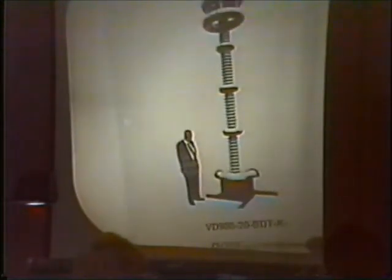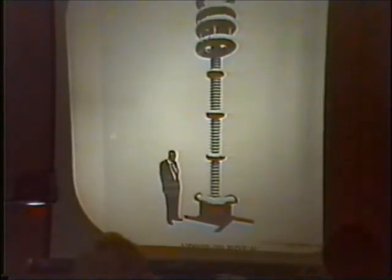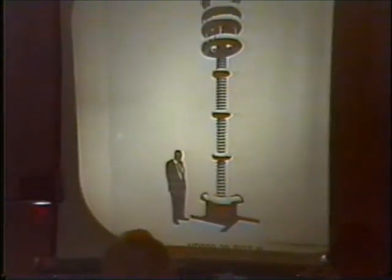Okay, well, here comes the 900,000 volt one. You see that it gets out of control real fast, as to the voltage dividers and the instruments that you have to use and that sort of thing. There's actually a much easier way to do this, and since magnetic flux and electrical flux are part of the same coin, it's real easy to measure the magnetic flux with relatively cheap instruments, hand-sized calculator size deal. You can measure the magnetic flux and you can convert that directly into voltage, and some of those meters that read the magnetic flux actually read in voltage.